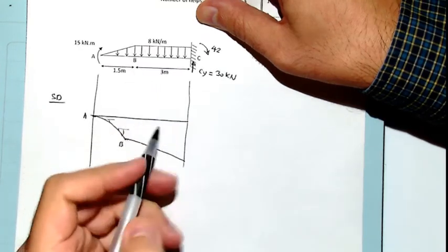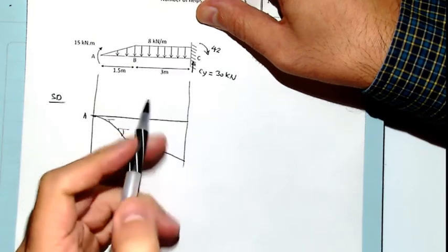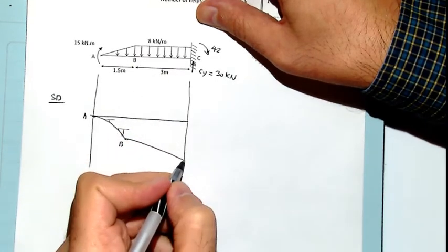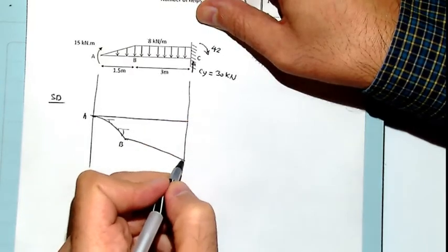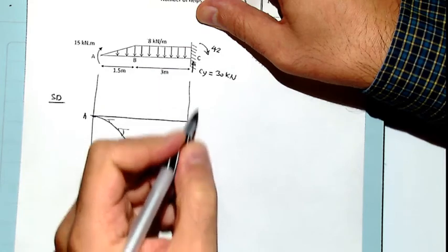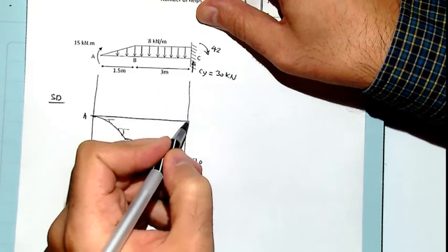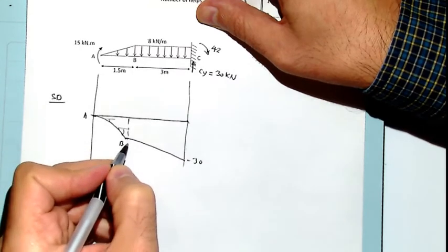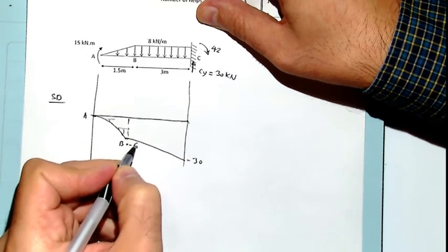And how much would be added to B is 8 multiplied by 3. Then at this point we have 30, and if you calculate, it's minus 30, and we add minus 30 plus 30, so we're going to reach 0, which shows that my calculation is correct. At point B it is minus 6.